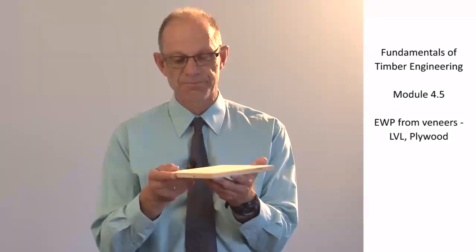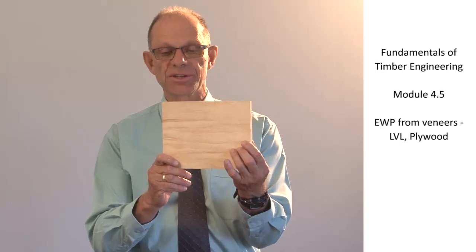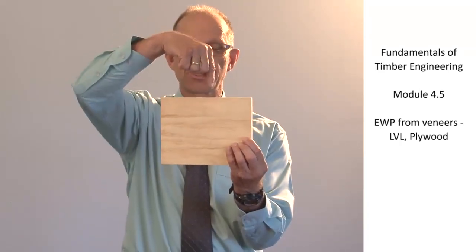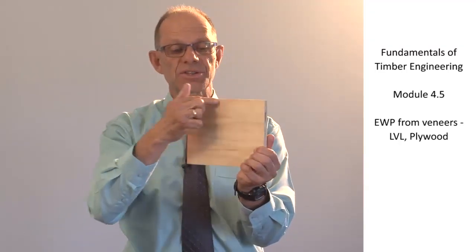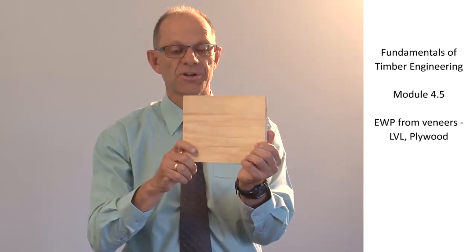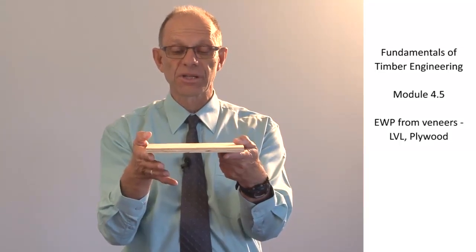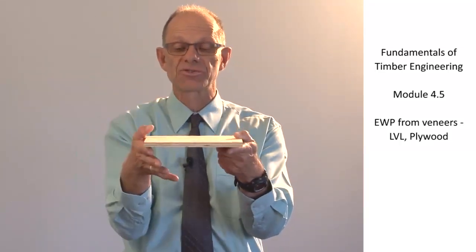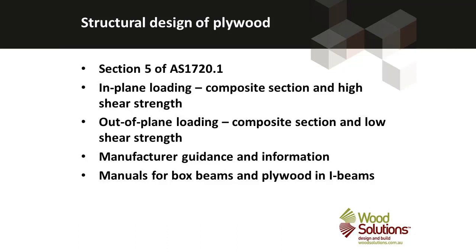The structural design of plywood considers two different variants. One is in-plane loading, where the plywood is essentially loaded as a really deep beam. So the loads for in-plane loading would be applied here, and stress is induced in this direction and that direction at the top and bottom of the sheet. Out-of-plane loading loads it very much like a floor. In this case here, the loads are treating the plywood as though it is a miniature slab. Both of them use composite section theory to analyse the plywood, and that is fully detailed in section 5 of AS 1720.1.